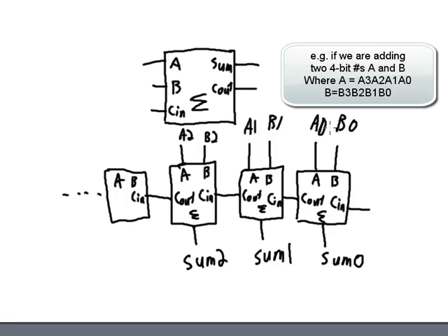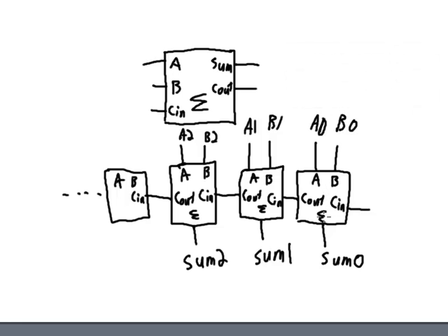And so the least significant bits of the 2 numbers, A0 and B0, get added together, and then it's got to go through some logic circuitry here. So there's actually some kind of propagation delay, a few tens of nanoseconds maybe, before sum 0 is created and before carry out is created. And similarly, over here, there's some kind of propagation delay between when A1 or B1 or C in changes before the sum 1 gets created.